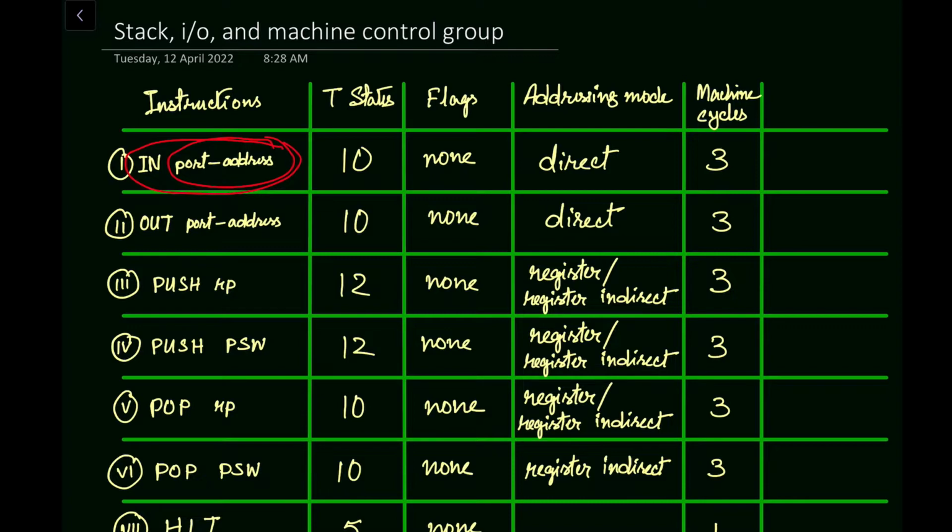Here you have to keep in mind that in the case of the 8085 microprocessor, the port address is 8-bit. The memory address is 16-bit because the memory bus is 16-bit wide. We already know that the accumulator content is 8-bit and the port address is 8-bit, so the data available at the port can be directly transferred to the accumulator.